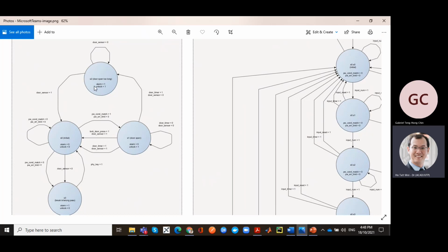Okay. So the other thing here is that there's a problem. The problem is when your door is open, this thing is still running. So I can still put in the right code and then it can actually lock. So there's a problem, you know, right? Because this thing can suddenly match or it can suddenly not match and then you latch things. So if it matches or doesn't match, then okay, I guess you have this state sort of defined, but you just have to double check. Do you want that or do you want some kind of signal to come back here that when you're in these two door open states, you pretty much force it back to state zero?